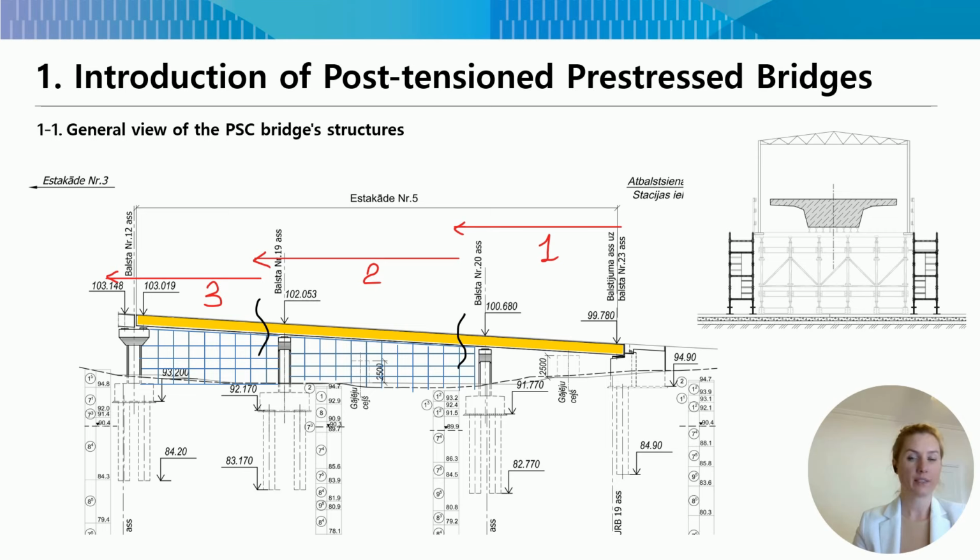Installation of technological shelters. Later, cast of the first span or first segment. When the concrete has gained strength of 80%, tensioning of tendons is carried out. Then anchor the tendons and install couplers to stress the cable in the next part of the deck, which has not been cast yet. After that, cast the second span. After the concrete has gained 80% of strength, tensioning occurs.